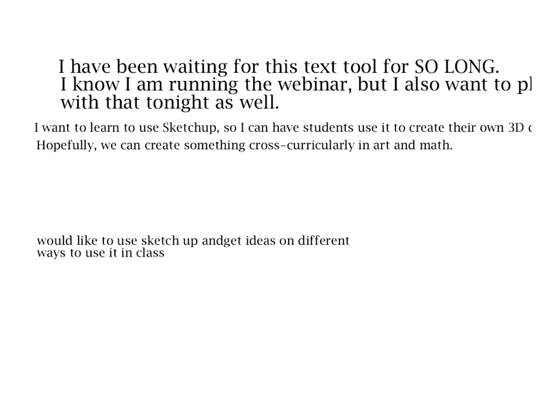So an easy example to kind of split the difference for you is if I wanted to create a house in Tinkercad, my easiest way to do that is to grab either a cube or a rectangular prism and drop it onto my workspace, stretch it to the side that I want, the size that I want, and then grab a triangular prism and stack that on top and stretch it to the size that I want.